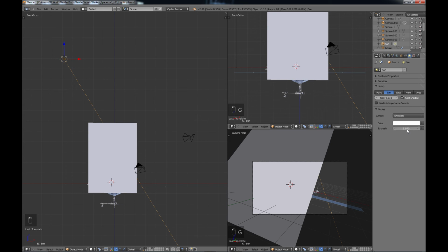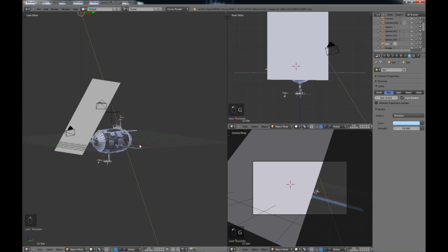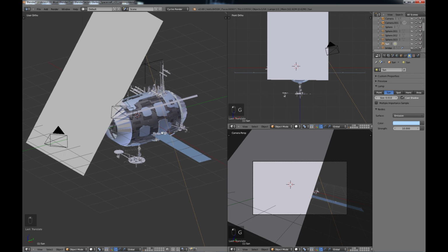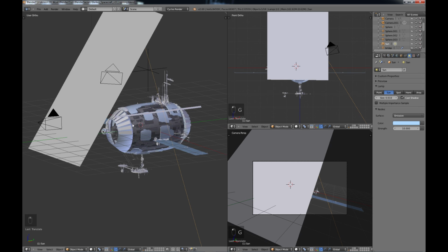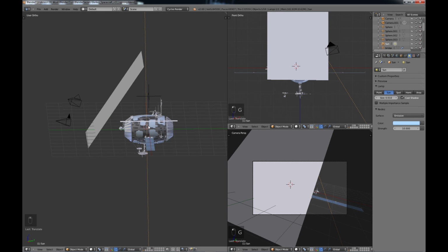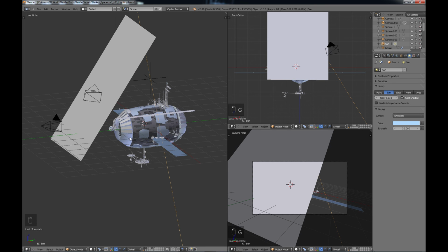And for the strength, I'm going to change that to 10. And color, let's go into the hex and change that to AFD9FF. And this is just a kind of a little bit more bluish color. Okay, and that is our basic light setup for now. We'll see how this turns out, and then of course, as far as light goes, it's a lot of tweaking where you want to play around with your lighting settings and make sure that they look okay.